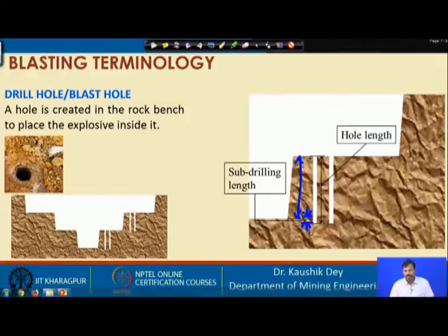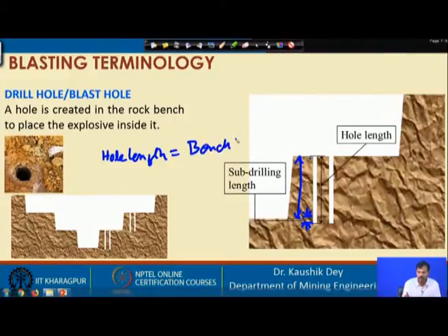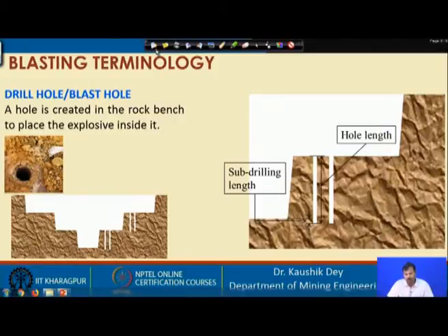This additional drilling carried out in the drill hole is called sub drilling. So, this is the sub drilling length, this is the bench height, and the total hole length is nothing but the bench height plus sub drilling length.